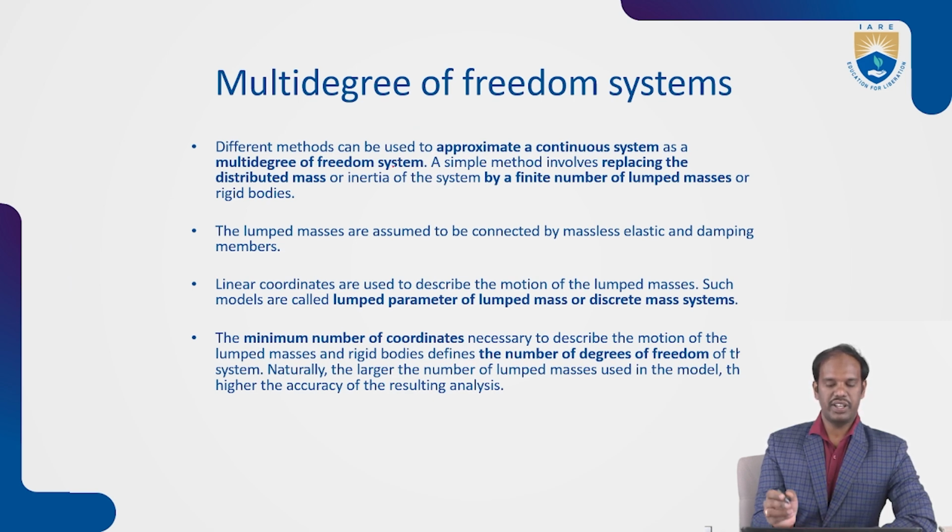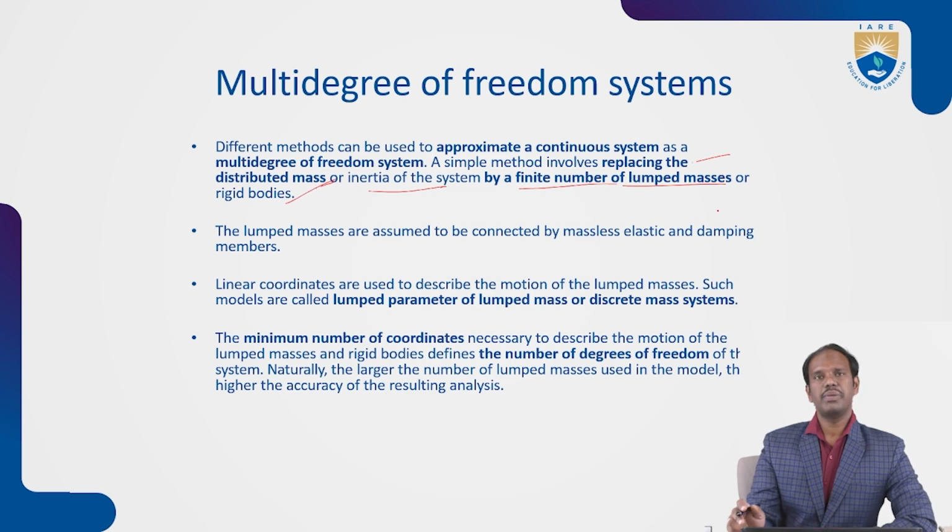Different modal methods can be used for approximate continuous solutions, which are taken as multiple degrees of freedom, by a method involving replacing the distributed mass or inertia of the system by a finite lumped mass system or rigid bodies. This is the finite element method or finite element models, which are used particularly to solve multiple degrees of freedom. It will be used as multiple lumped masses or inertias of the particular system.